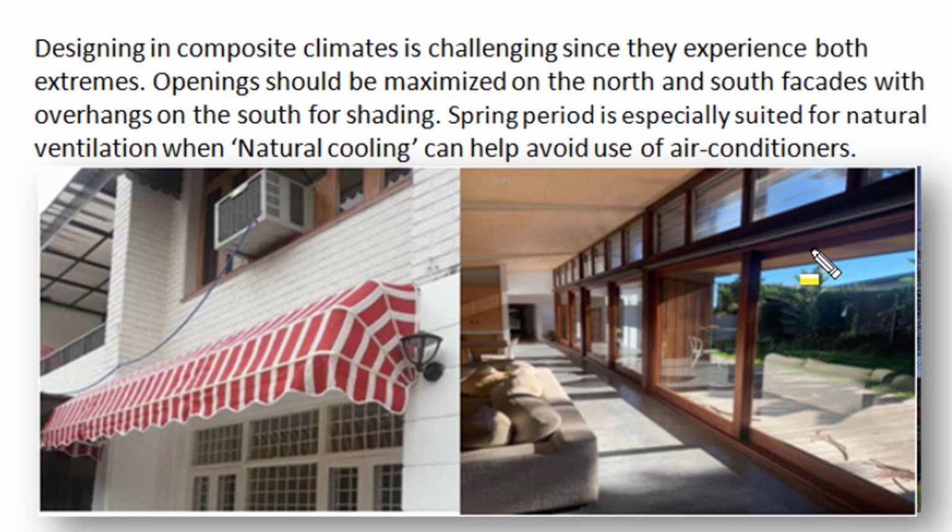In summer conditions, we must provide horizontal projection over fenestration as shading, and they may be permanent overhangs or temporary shading arrangements on fenestration so that we can stop summer solar radiation by shading and low angled winter radiation, which can generate comfortable temperature conditions in indoor space, can be allowed to pass fenestration, as these horizontal shadings won't obstruct winter low angle solar radiations.